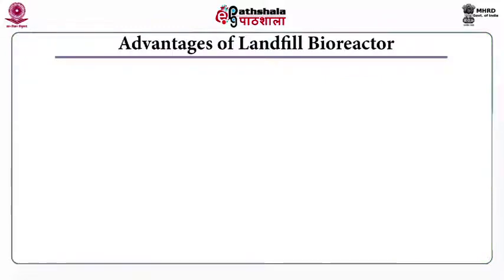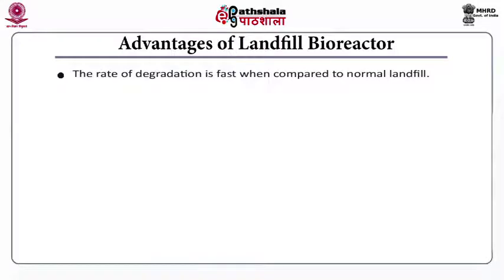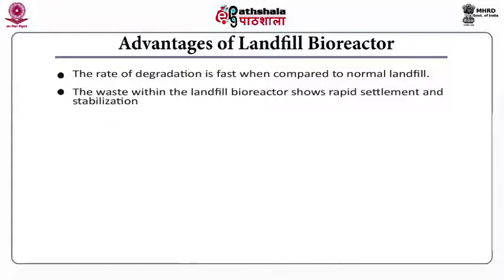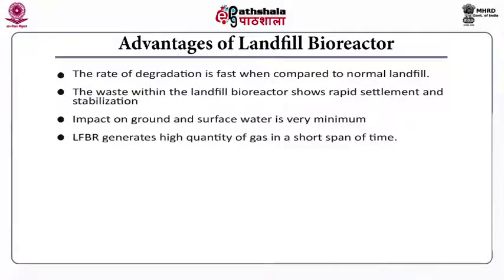Now, let us look into the advantages and disadvantages of a landfill bioreactor. The rate of degradation, since it is faster in a landfill bioreactor than a conventional landfill, becomes a major advantage. The waste within the landfill bioreactor shows rapid settlement and stabilization. The impact on the ground and the surface water is very minimal, and they generate a very high quantity of gas in a short period of time, which is again a major advantage. The greenhouse gas emissions are generally reduced, which is again one of the major advantages of a landfill bioreactor.